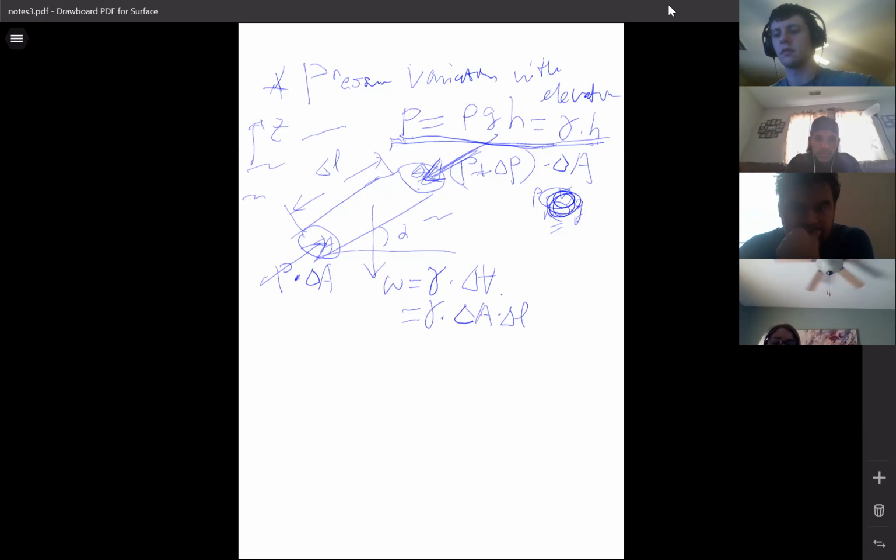So after the free body diagram, you ask yourself, am I going to write the force balance equal to 0 or moment balance equal to 0? That's two options, two routes to solve a problem. You have to pick the correct one. In this problem, there's no rotation considered here, so we should try force balance first. In the hydraulic jack problem, remember the lever? You have to rotate it, then obviously we go through the moment balance route. Here we want to try force balance first.